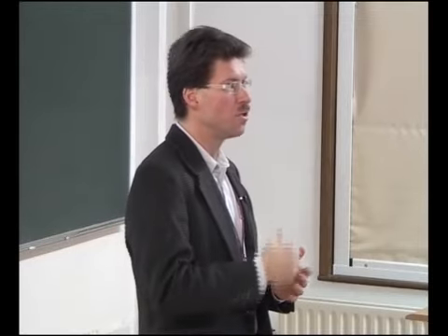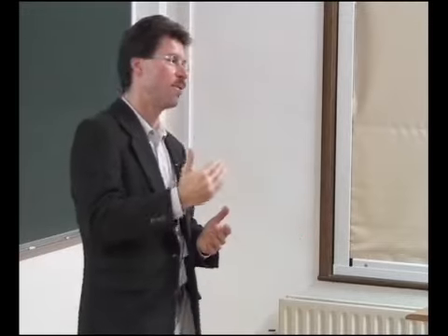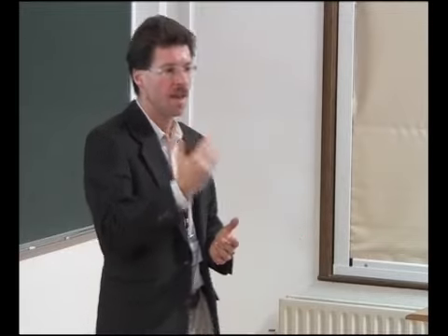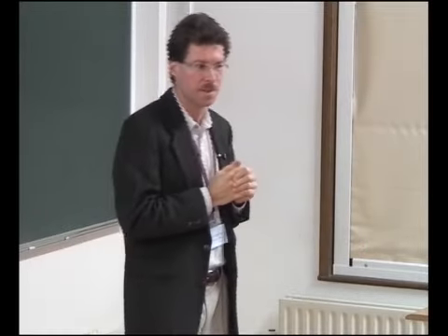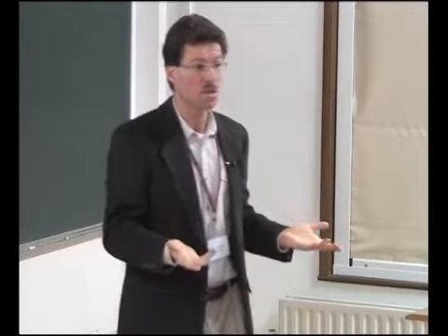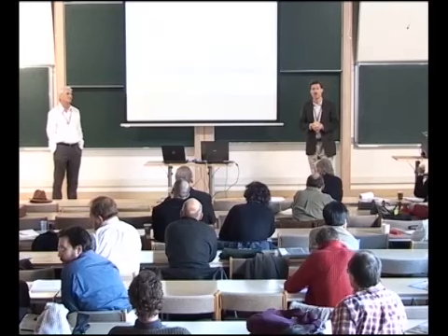What's the advantage over just using a point vortex method? I mean, you're using point vortices to absorb all of your errors, but you could just use point vortices for the whole thing. The simulation I compared with was a straight vortex-in-cell method using a high order, well, it wasn't bicubic, but it's the M4 scheme, which is considered the holy grail of the interpolation schemes in vortex methods. So we use that, and you can still see that a huge diffusion takes place in these methods.